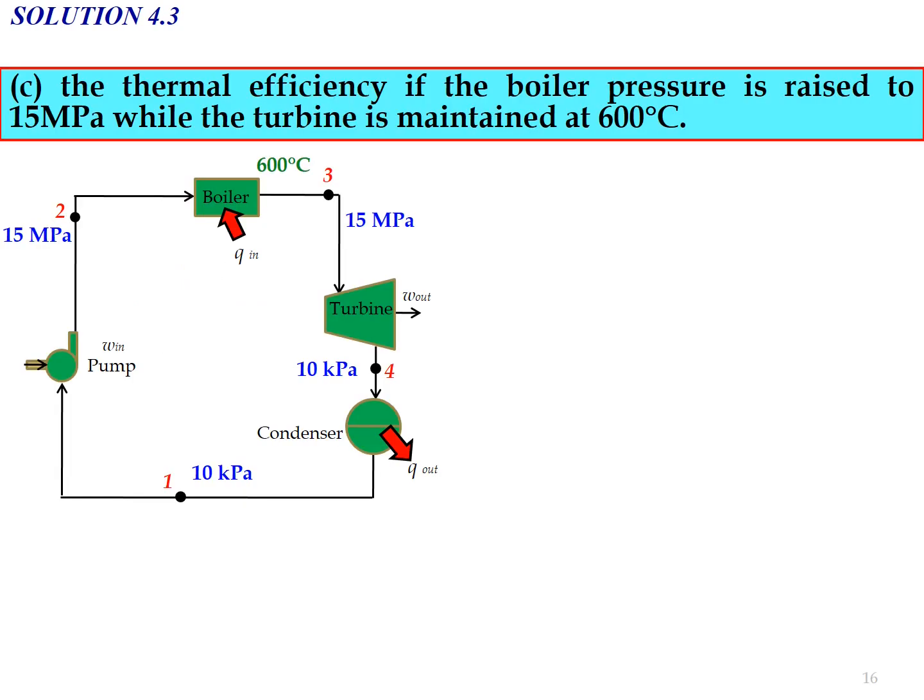Okay, for question C, you need to recalculate the thermal efficiency if the boiler pressure is raised to 15 megapascal while the turbine inlet is maintained at 600 degrees Celsius. If you compare to question B, the temperature T3 is fixed at 600 degrees Celsius, but now the change is the pressure of the boiler during the heat addition process. Instead of 3 megapascal, now the pressure increased to 15 megapascal.